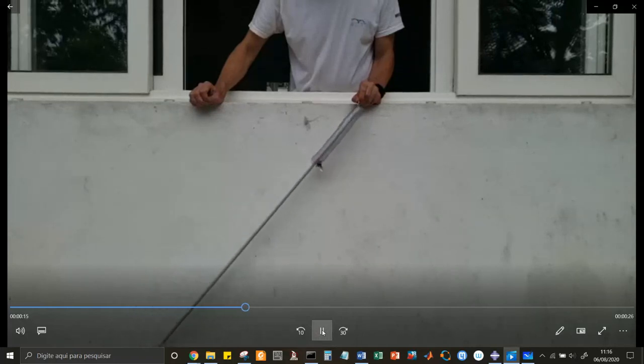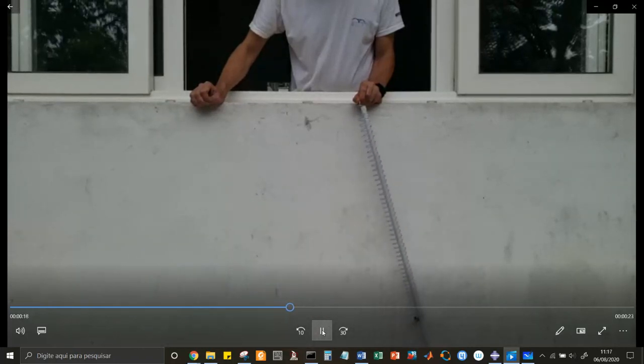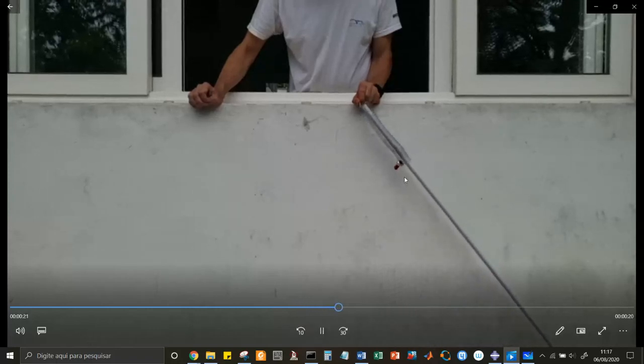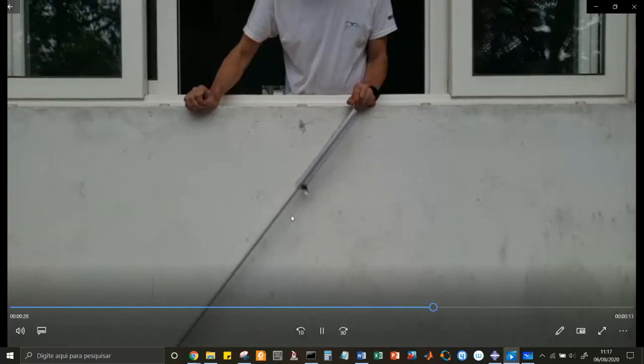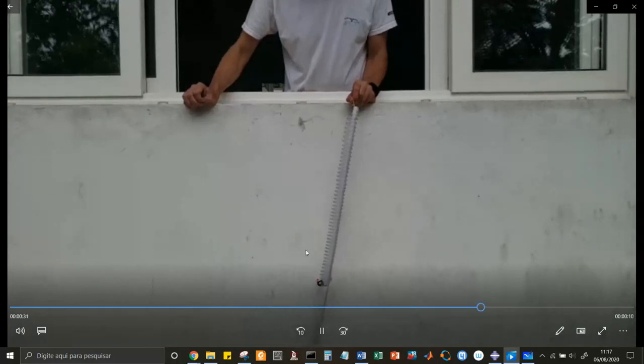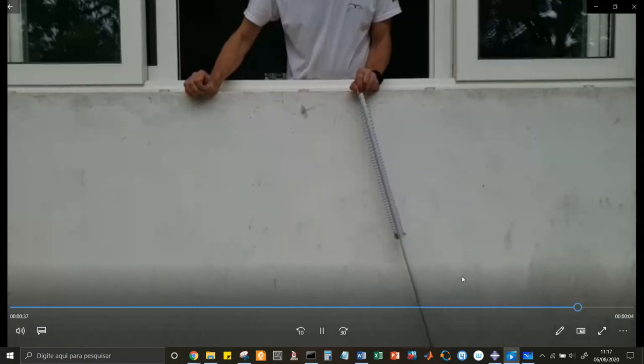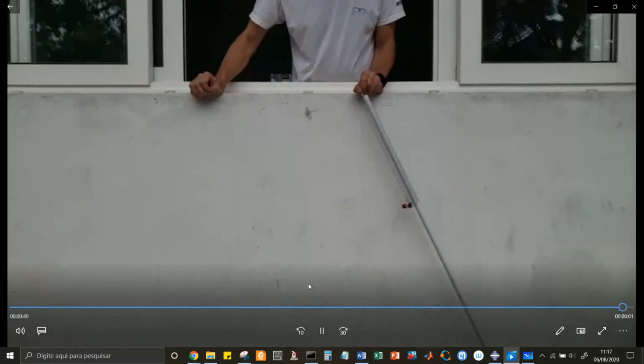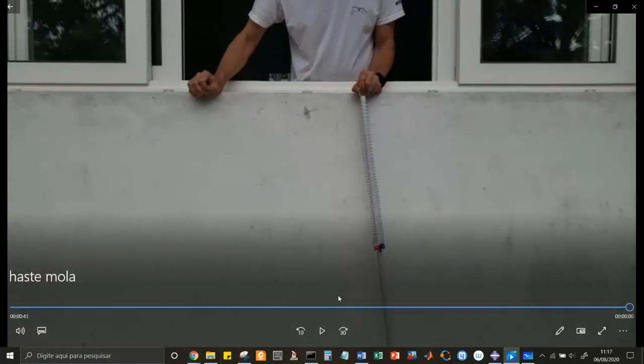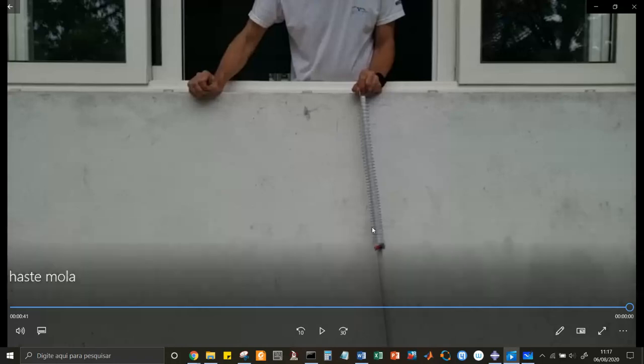So we wanted to model this in Abaqus, and for that I'm going to use a rigid mass as the nut, representing the nut, a spring connecting this point to the mass, allowing this motion and this motion, and the rod is not going to be considered in the model in Abaqus, but could be, if we could add the inertia of the rod connected or concentrated on the mass, or to have really a rod as a piece in our model, as a part in our model.